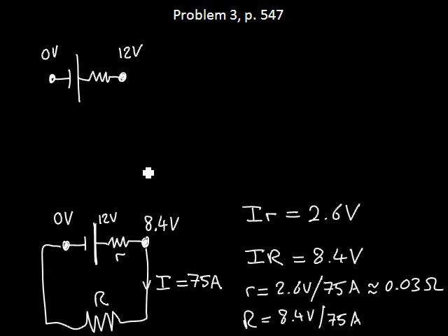So the internal resistance of the battery is usually small. It's always in series with what's outside, and there's a voltage drop across it, but you're only going to see that when you start having a current flow, when you close the circuit by connecting the terminals of the battery. And if you think back to the experiment you did with Ohm's law, when you had those wires and you were connecting to them, you saw that voltage drop on the voltmeter when you connected the circuit and started current flowing through it. That was a result of the internal resistance of the batteries you were using there.